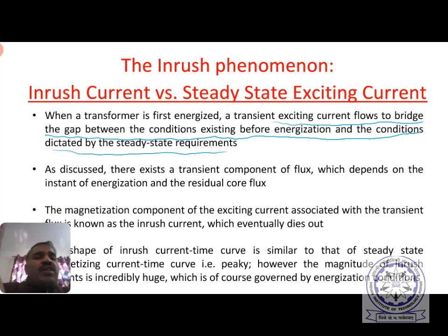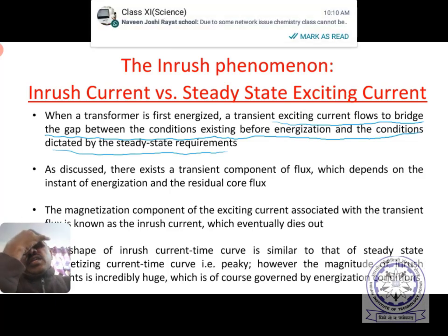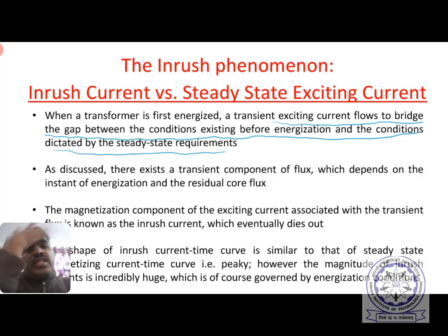In any circuit or system with a steady state operating condition, if you switch on in such a way that the steady state conditions are not disturbed, then there will be no transient. Or if you switch on the system at its natural zero, then there will be no transient, a natural zero phenomenon, not voltage zero or current zero.